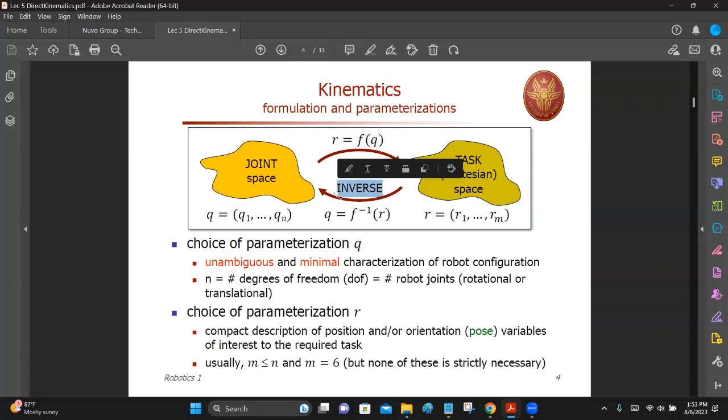So most of the industrial manipulators, what they do, a very simple technique, is that once you bring the manipulator to wire points, point 1, point 2, point 3, and so on, the robot manipulator doesn't know X, Y, Z where you brought the end effector to. The robot doesn't know. But the robot can read the joint angles. The first joint angle 30 degrees, second joint angle 50 degrees, like that. It can measure all of these joint angles. That's all it needs.